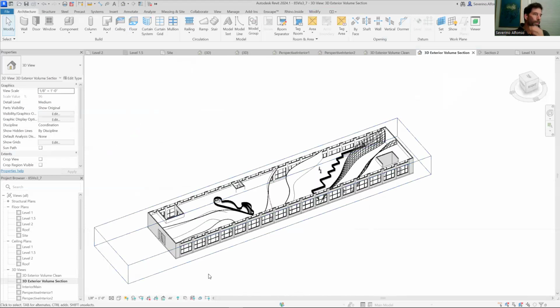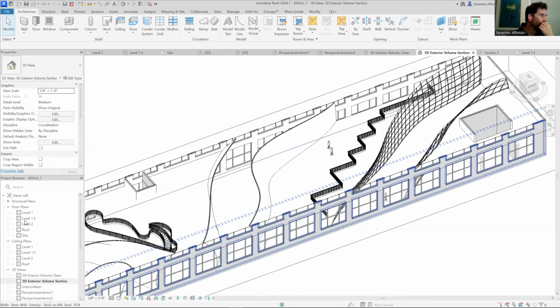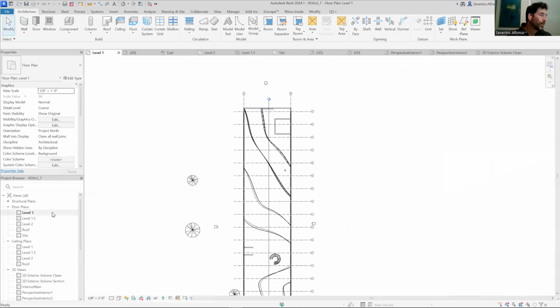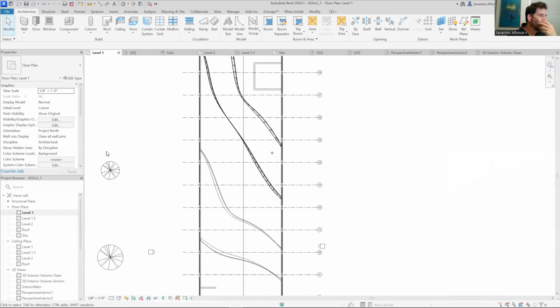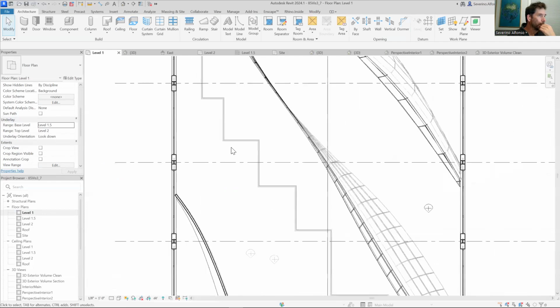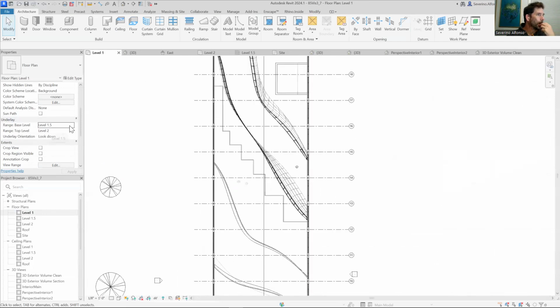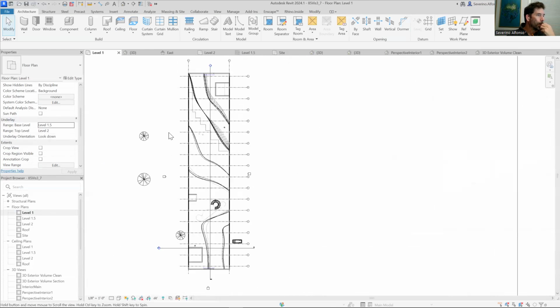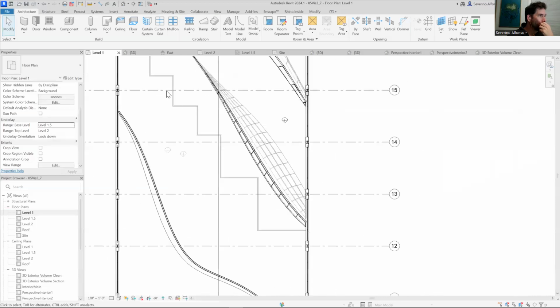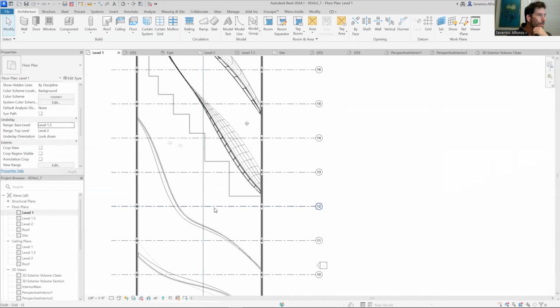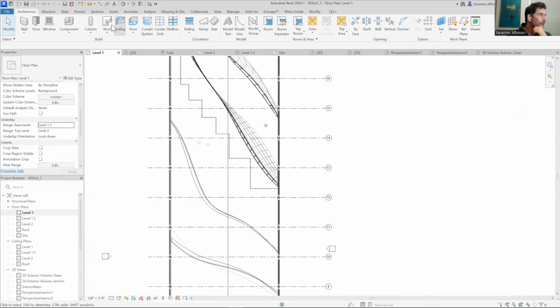Just working on things. You could create another stair going to that point. That would be level 1 because we go to the lower floor. If we want to see a little what's above us, we can always go for a little bit to the underlay and say, I want to see level 1.5. Whatever you place on the underlay, it's shown in light gray. That means that you might leave it, but typically I recommend it's considered temporary. So you remove it afterwards. You go to none again here. But it's good reference to see where it is while working on level 1, what's happening in level 1.5. It's a great tool. I'm going to do a stair.